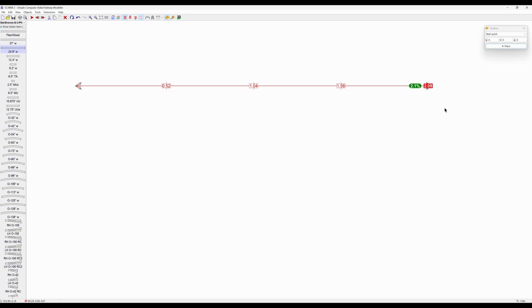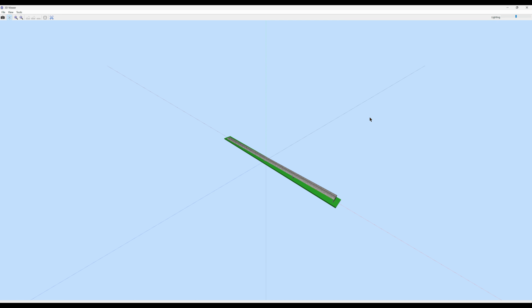So we're using the green oval that SCARM provides calculations on. You can see it turned yellow, and we're on the fringe of 2.5%. So we'll bring it back into green, and that actual elevation increase on the end of that track was 2.44 inches. We're in empirical units. And there's our look at it.